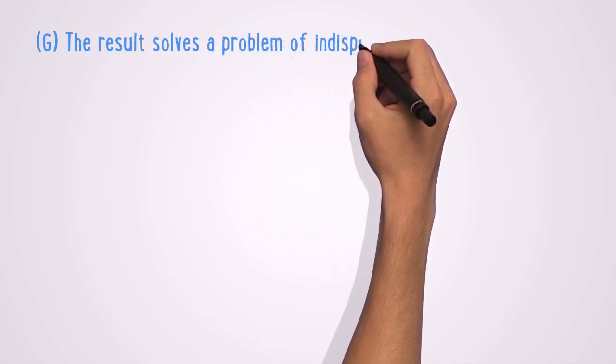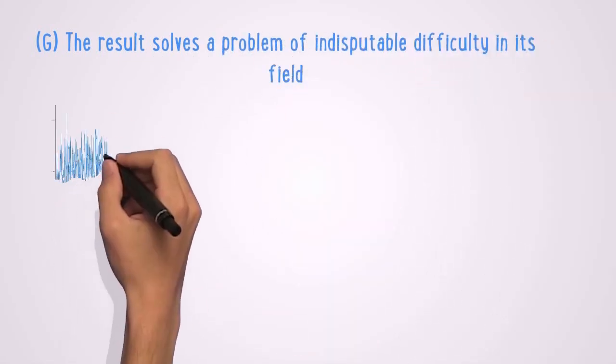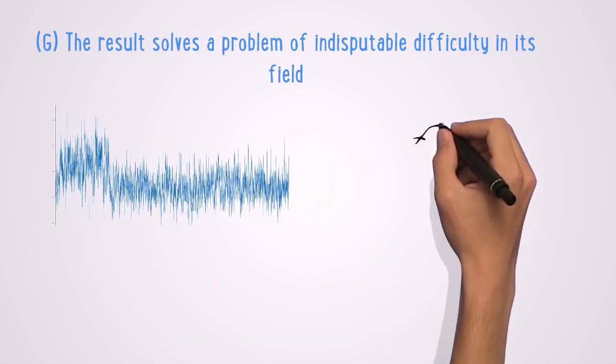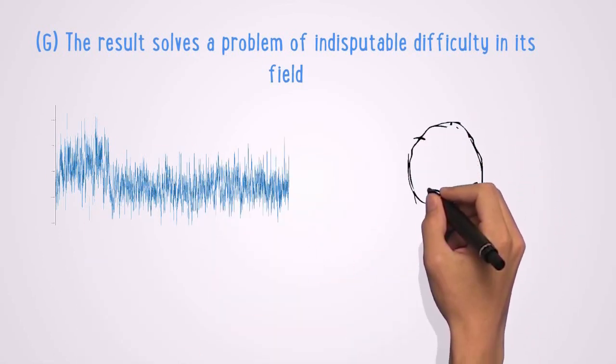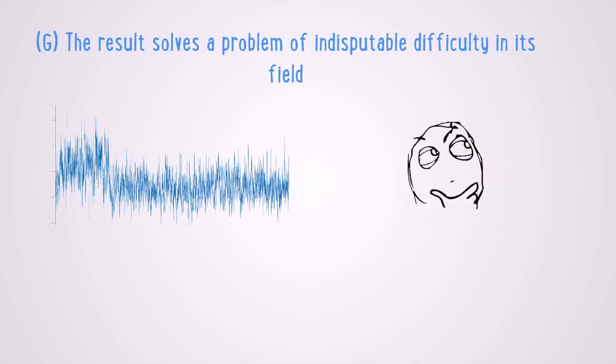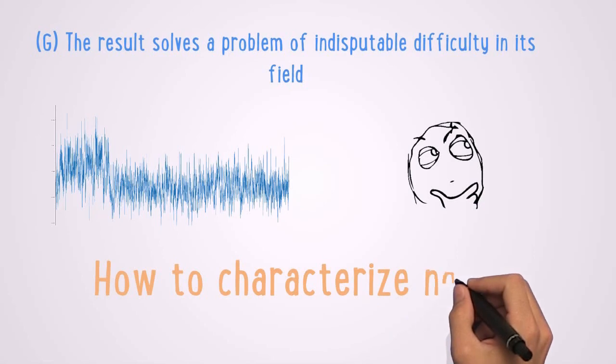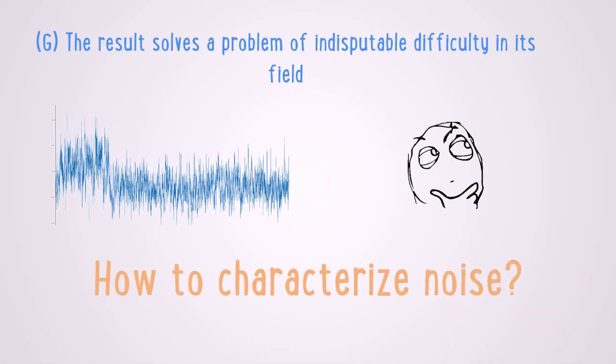Finally, criterion G is fulfilled since this problem dates from the conception of the Kalman filter. The optimality of the filter is based on the proper choice of the unknown covariance matrices of a zero-mean distribution to model uncertainty and noise. However, in practice, noise is not necessarily either Gaussian noise or even Gaussian with a constant covariance matrix.